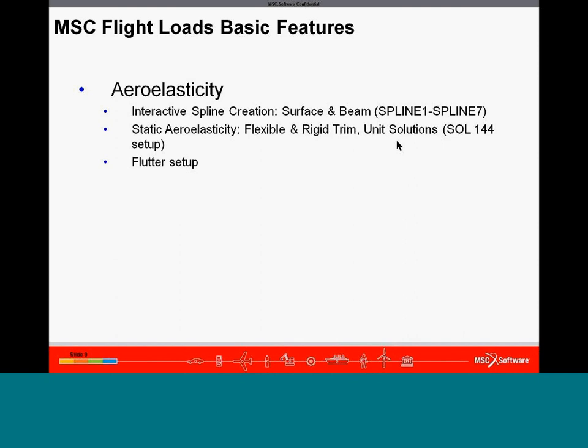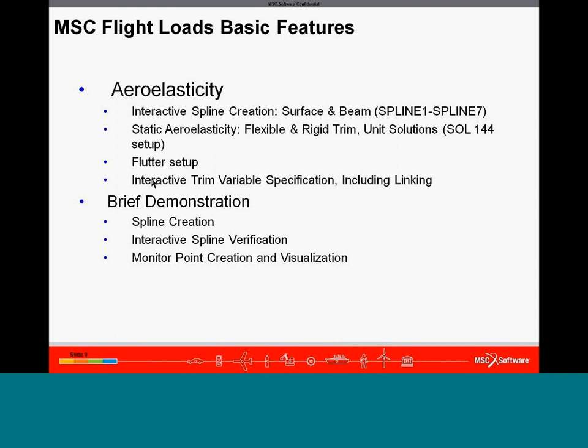Also on the aeroelastic side in Flightloads, you can create the static aeroelasticity setup, so you can define the controllers and the trim model setup. You can also do a little bit of the flutter setup and export the Nastran model to do the aeroelastic analysis. So let me give you just a brief demonstration on the splining side, and if I have a little time, I'll also show you a little bit on the monitor point side.